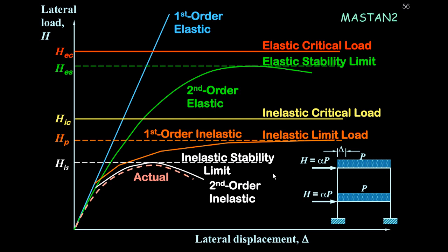The thought here is it's starting to fall over, and the only way you can keep it in equilibrium and freeze the analysis is if you were to take off load. So you're still getting positive deflections and you're pulling load off, and that's the definition of an instability. A lot of times what you'll see is an unloading that takes place once you've reached any form of an instability. It's basically saying, I don't care if you take load off, I'm still going to get more deflection. So I think that's about as quick an answer as I could give you.